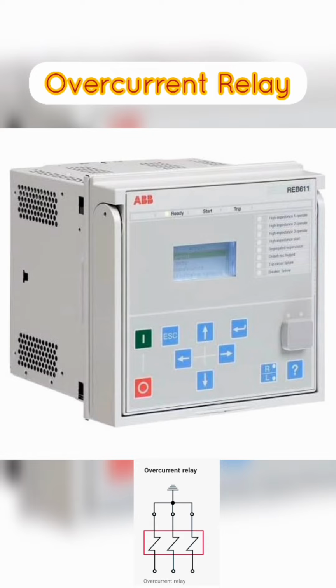Overcurrent relays are typically designed to operate within a specific current range and have adjustable settings for current sensitivity, time delay, and trip curve. The trip curve is the graph that shows the relationship between the fault current magnitude and the time it takes for the relay to trip. In summary, overcurrent relays are an essential part of electrical substation protection schemes, providing reliable and fast protection against overcurrent conditions that can damage the equipment and cause power outages.